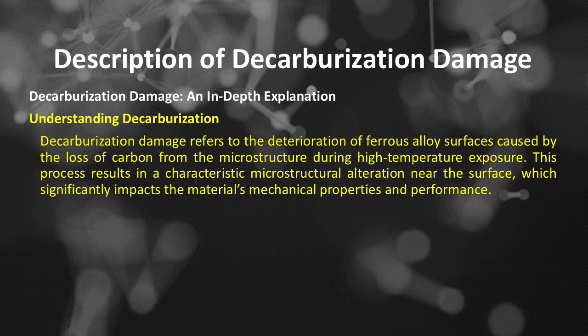Understanding decarburization. Decarburization damage refers to the deterioration of ferrous alloy surfaces caused by the loss of carbon from the microstructure during high-temperature exposure. This process results in a characteristic microstructural alteration near the surface, which significantly impacts the material's mechanical properties and performance.